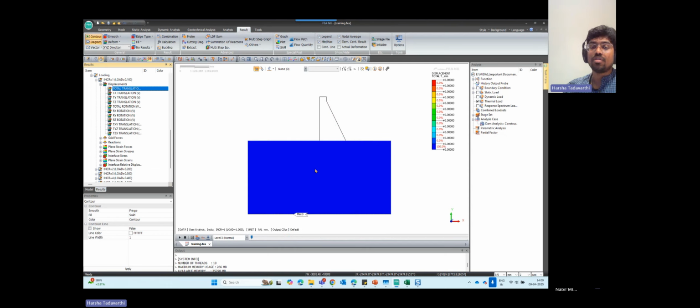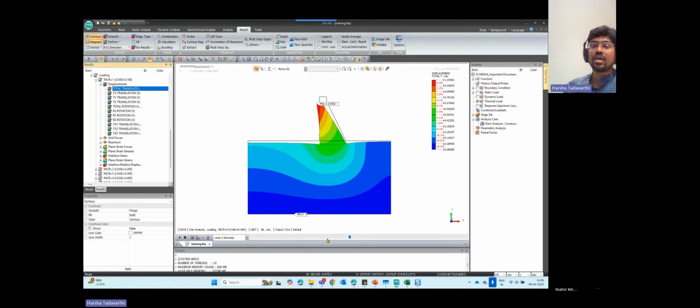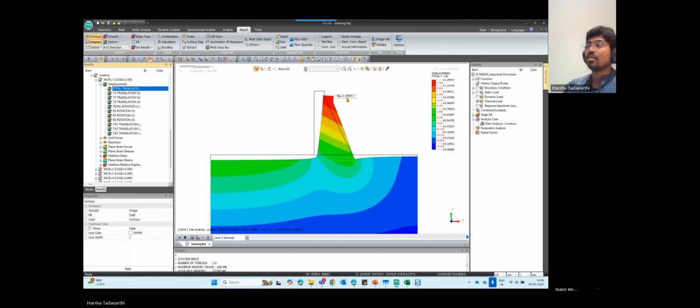Initially we have a 0. And then when the dam is placed, it is displaced onto the upstream side by 1.57 mm. As the loading of the water proceeds, we can scroll down to see step by step. You can see the value is decreasing, and later on it is increasing. The max displacement it went to on the upstream side is around 1.3 mm. So it's very small. The displacement is almost negligible. The dam is almost safe here. Okay. Then the next thing is to see whether the tension crack is happening or not.